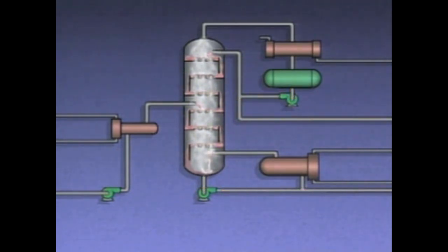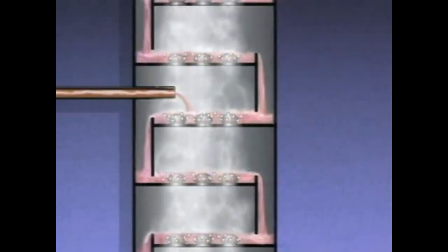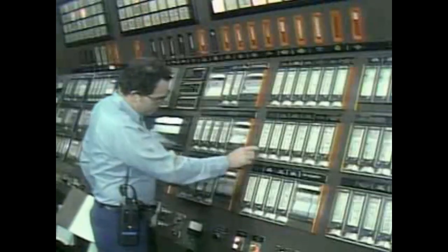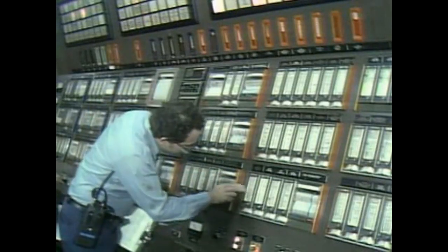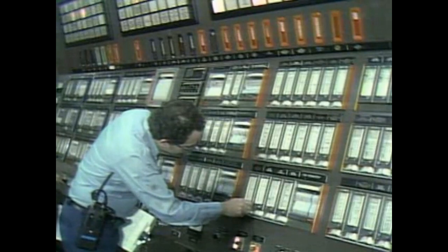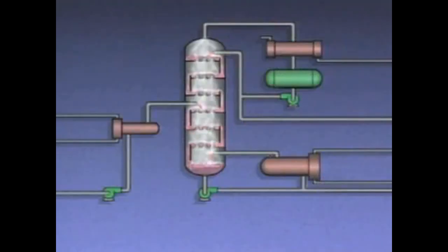To correct a low feed rate problem, the cause of the problem has to be identified. If a feed line blockage is detected, it must be cleaned out so that the feed rate can be restored to normal. If an instrument reading seems unusual, it should be reported. In the meantime, the feed rate may have to be controlled manually.